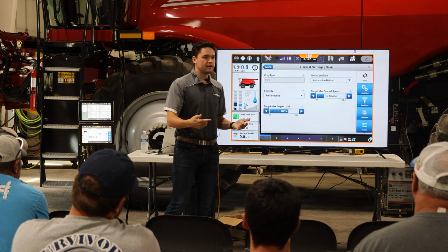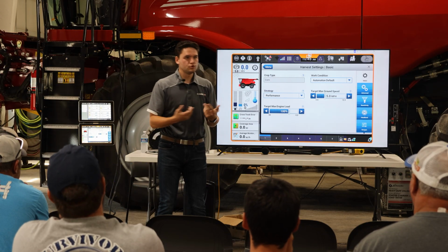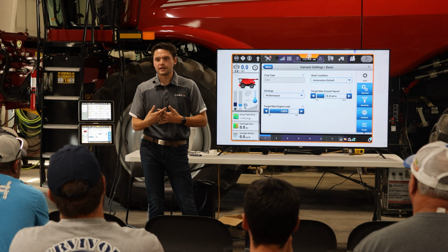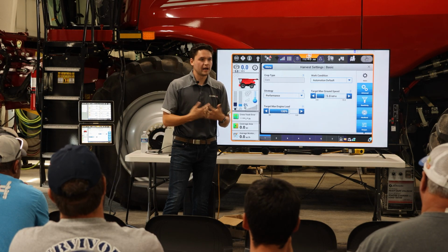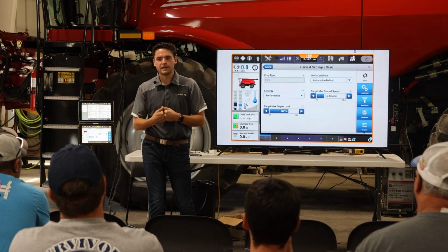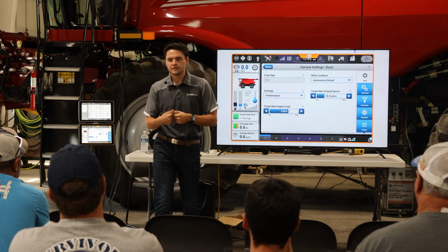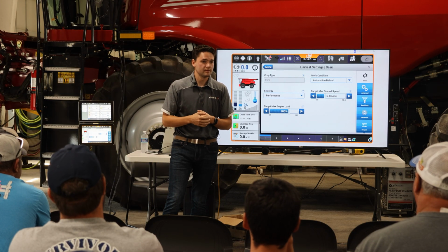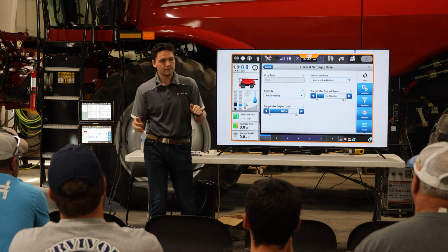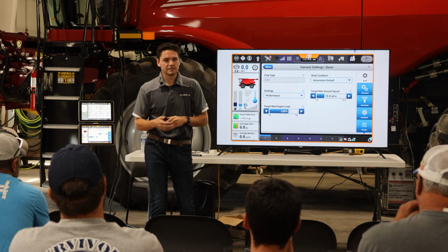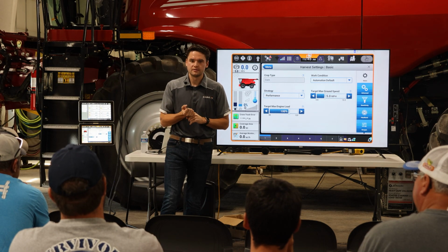So if we do that at 2 miles an hour and 30% engine load, and we want to run 5 miles an hour, what happens when we press the button to engage it if we calibrate it at 2 miles an hour? Right down to 2 miles an hour. It might slowly creep up, but the first thing it will do for sure is go to 2 miles an hour because that's where we did the calibration.